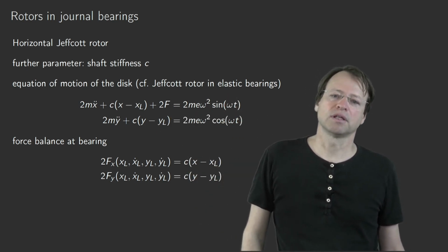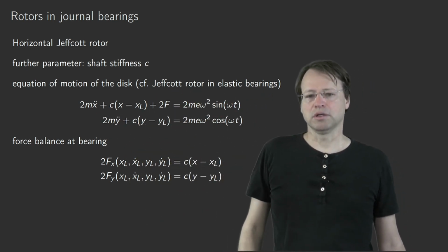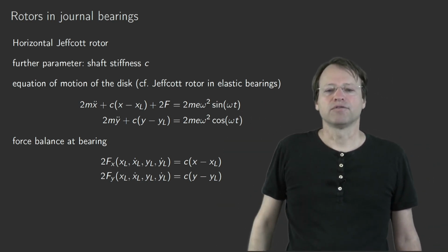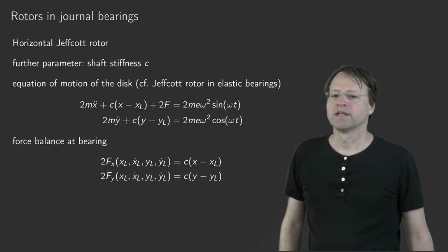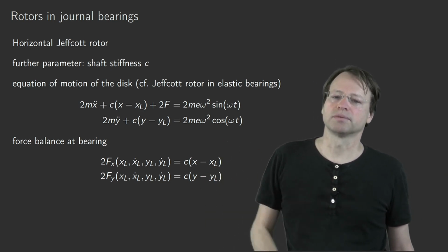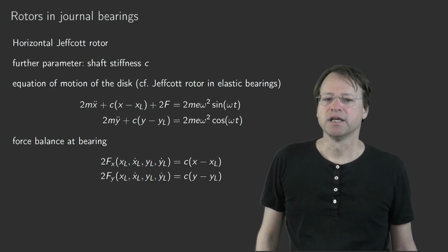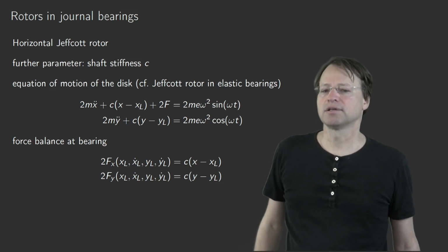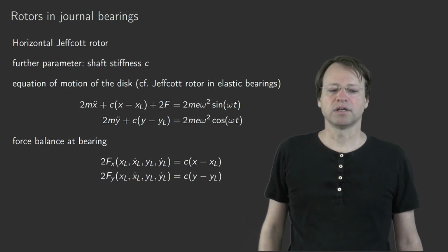In order to obtain something dimensionless, as we have here a sum of all the forces, if we interpret the inertial forces in the sense of D'Alembert, we have to divide by f. We also have to divide the static force balances by f. So we would obtain C divided by f, and then for x we have to introduce a dimensionless displacement, for which we use the clearance. So we have the product of C times the clearance divided by f, or 2f, which is the dimensionless parameter we can introduce here.